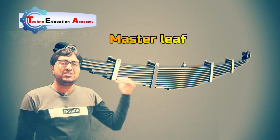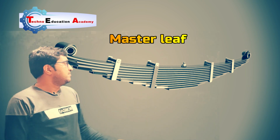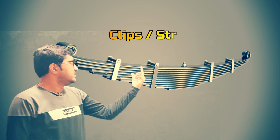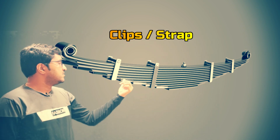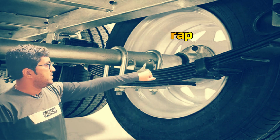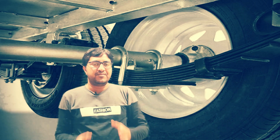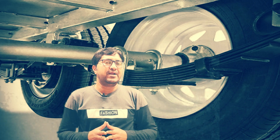This spring consists of a number of leaves, called blades, and these blades are bound with clips or straps. Here you can see a bundle of blades bound with clips or straps, and it is supported on the axle with a U-bolt. This is the U-bolt, and we can use it in front suspension as well as rear suspension in case of a heavy loaded vehicle.